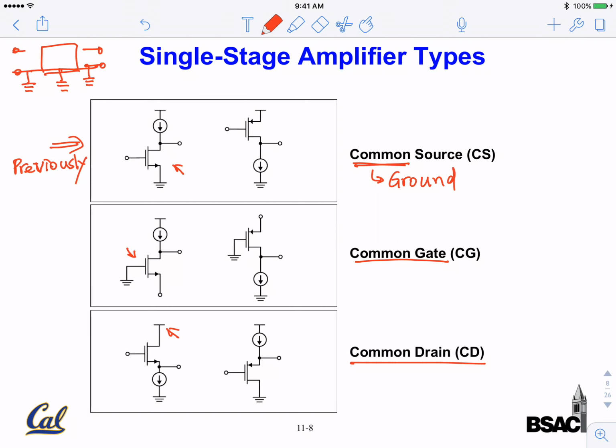Very quick overview. So you could, for example, draw the small signal circuit. These are also very easy to analyze circuits. And this is the small signal equivalent circuit, R0. This is gm VGS. And VGS here is basically equal to the input in this particular case. So you apply input here.